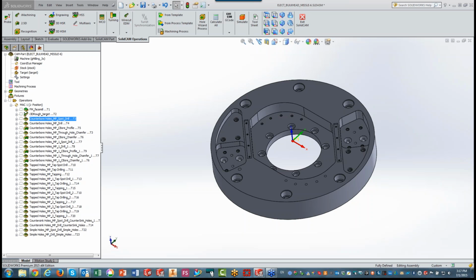They have G83 where you can go up all the way, go to your clearance level or go all the way down, keep it down. There are all different possibilities. So not every single controller is the same. Okay, so when I change machines, the process that I'm using now for this particular hole wizard is not correct.